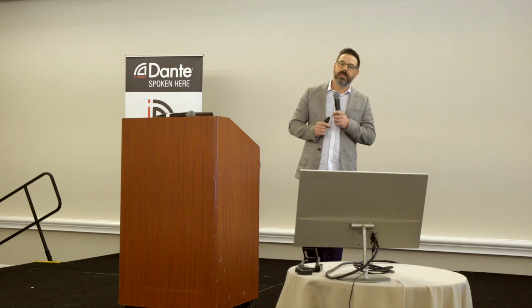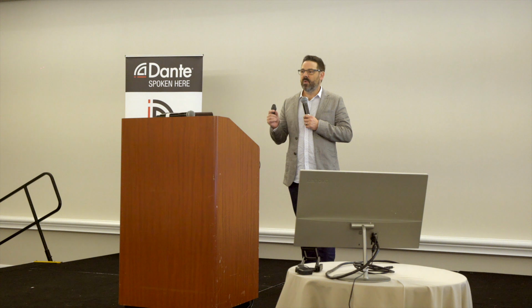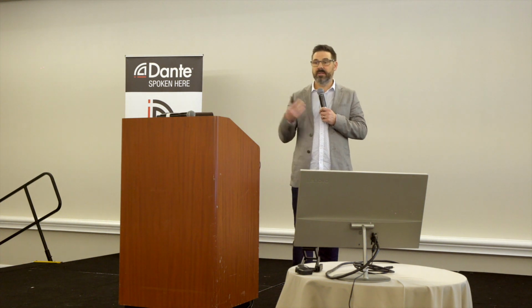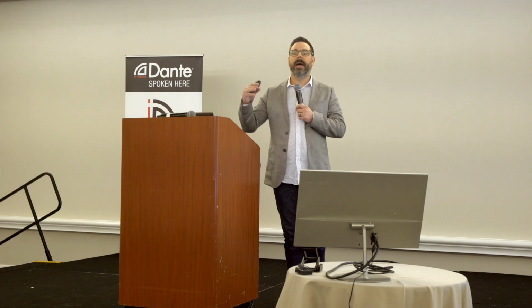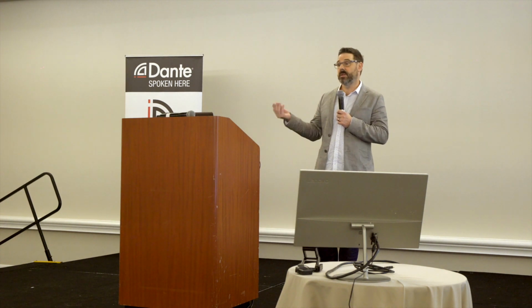But it's very, very limited in scope. It's designed for interconnecting two systems together, not to become the basis of a complete system. So you wouldn't build an AES-67 system in the way that you would a Dante system and expect it to just work.